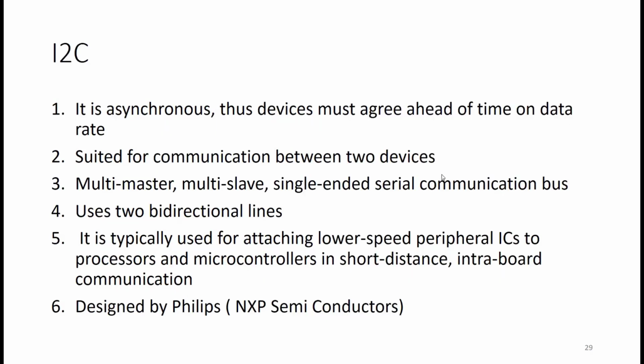Next, a very interesting and the easiest to support protocol is the I2C protocol. It is easiest because you need to identify only two lines: one is the SDA data line and the other is the SCL clock line. It is basically a synchronous communication where you can have multi-master and multi-slave on the single line of data and clock.